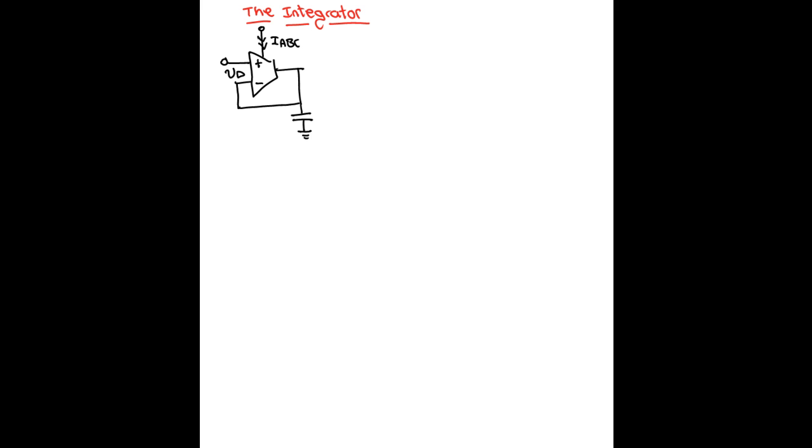You can note some of the similarities with the current control resistor, like the feedback, negative feedback. Okay, so let's start with AC analysis. And so it's going to be assuming a constant bias current. And you're sweeping the frequency up and down, see how the circuit performs.